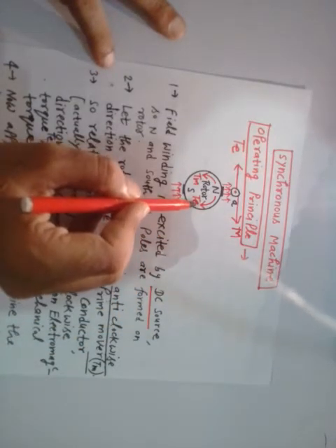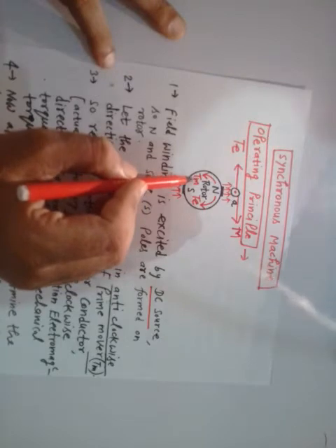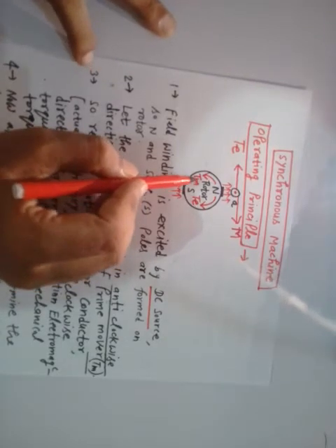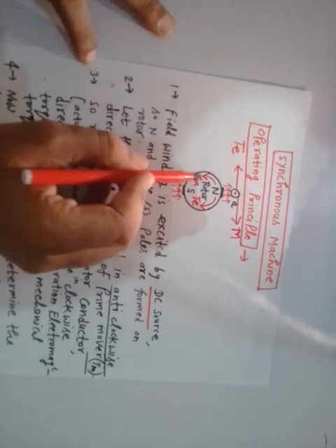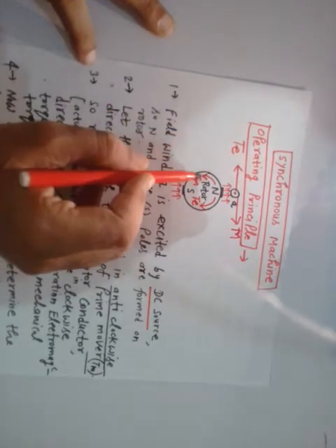You understand now? Suppose further electrical load is increasing on this synchronous generator, then what will happen? The electromagnetic torque will further oppose the mechanical torque, and the same amount of mechanical input it will draw from the steam input side.